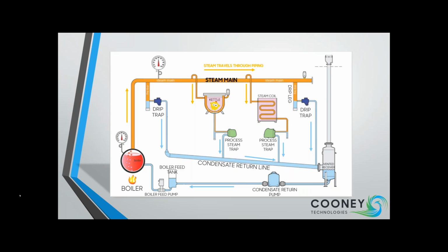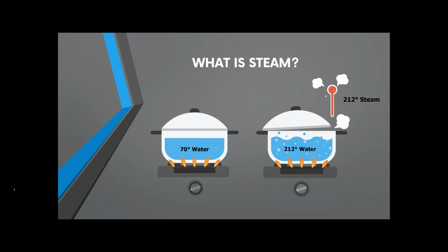At the pharmaceutical plant, I put exhaust heads on top of every vent line because one of the main engineers was walking on the roof one day when the flash steam was coming out. Even though the outlet was about 6 feet above the roof line, he got doused pretty good with a rain cloud of water. And after that, we put on the flange and an exhaust head.